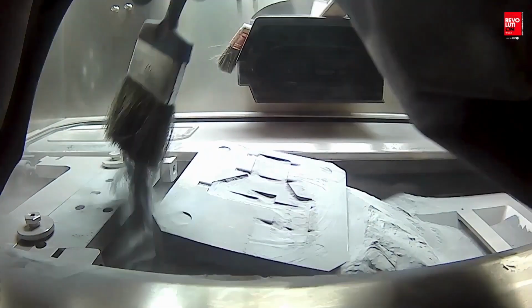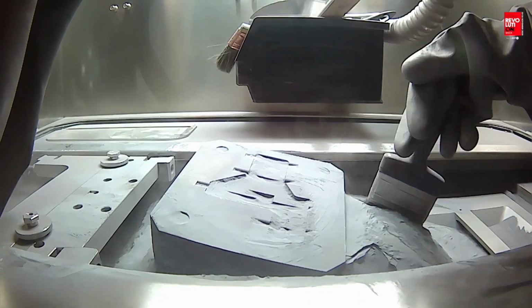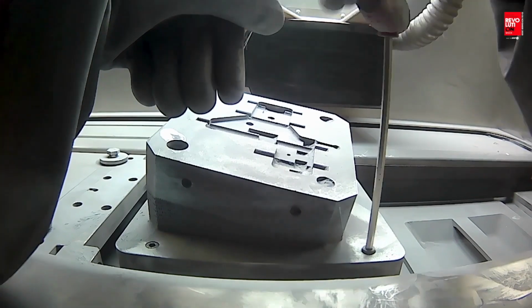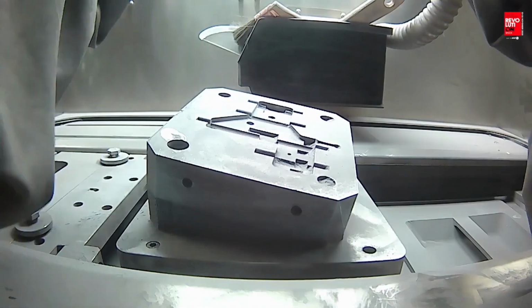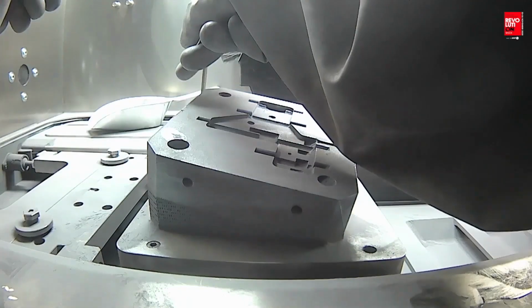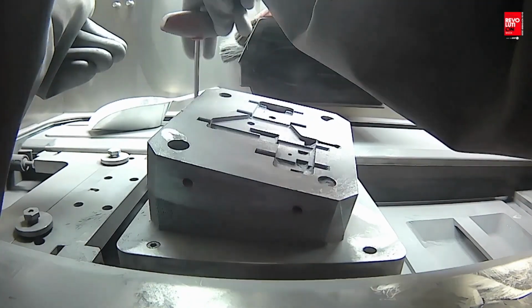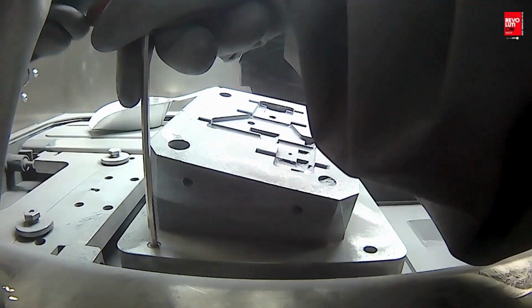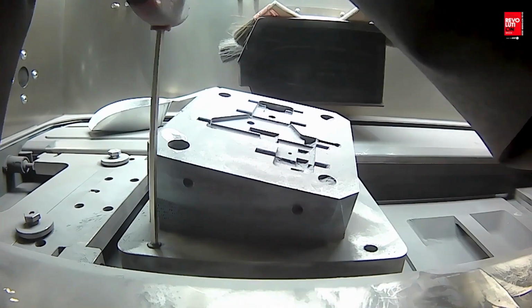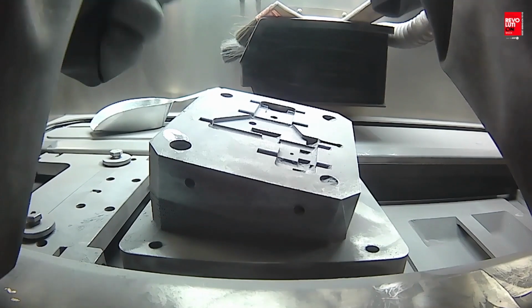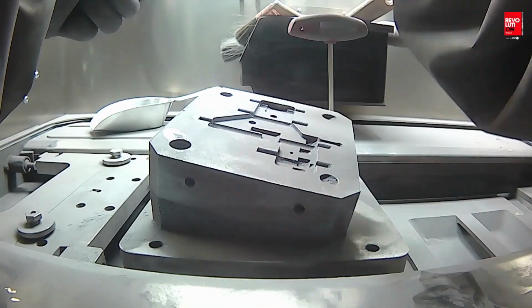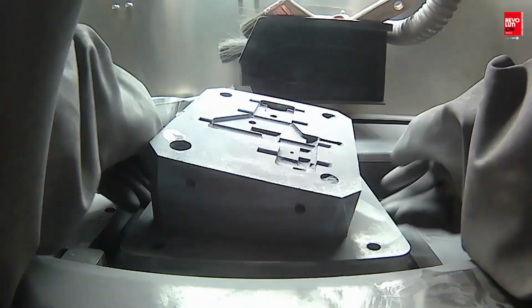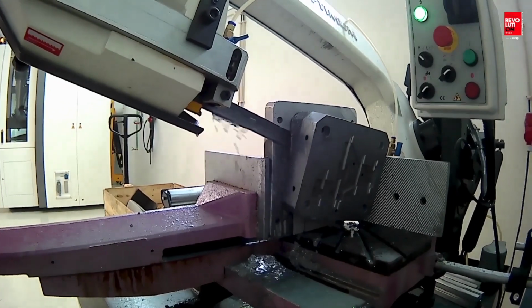The frame is screwed in a platform, and this platform should be removed from inside the machine. You can see also some supports, and these supports should be removed using a milling machine in order to cut all the supports that are in contact with, in this case, the insert molding part.